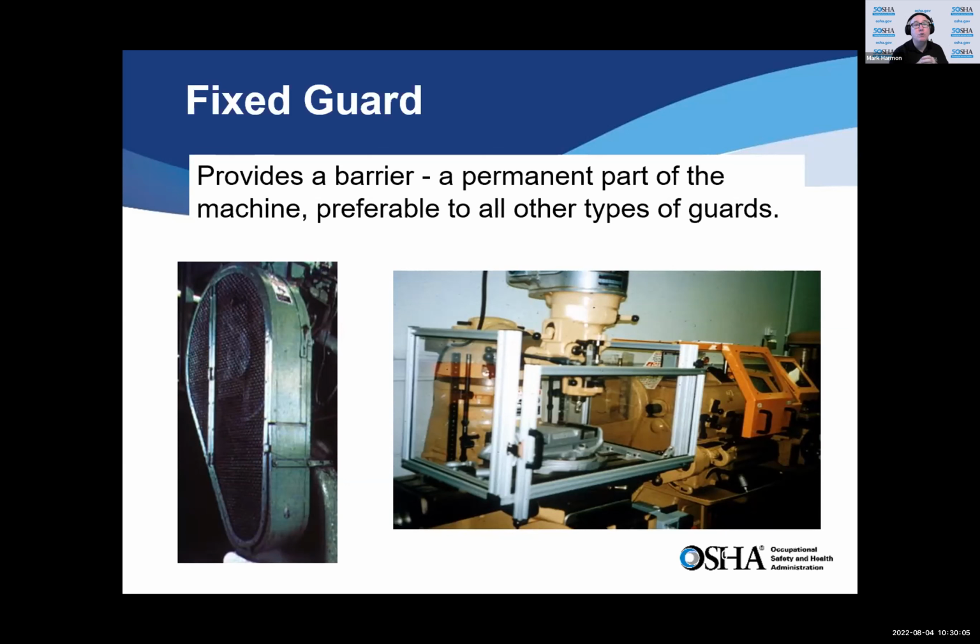So if you tell me how big the opening is, I can tell you how far away from the actual hazard it must be. And again, we have sort of a scale that we use. It's in the OSHA regulations that's sort of acceptable, in that the larger the opening, if you can imagine, the farther away from the hazard you need to be.